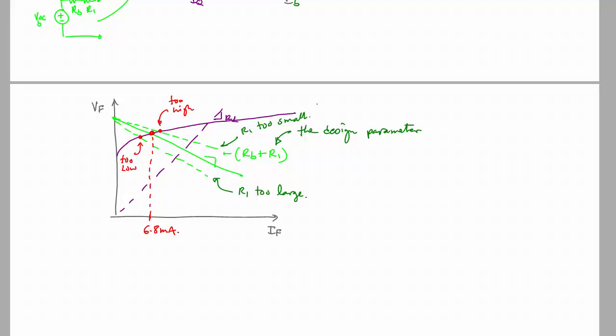So what you will do is actually graphically, you can do this in your lab book. If you have plotted data as you measured the LED diode current and voltage, and if you plot that on a scaled plot in your lab notebook, you can then draw this load line, and literally what you will do is you will know the open circuit battery voltage, VB open circuit, that you're going to measure. That's easy to measure, right? You just measure the voltage coming out of the battery when there's no current. And then you will pick what current you want to operate at.